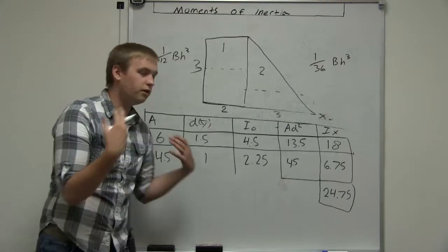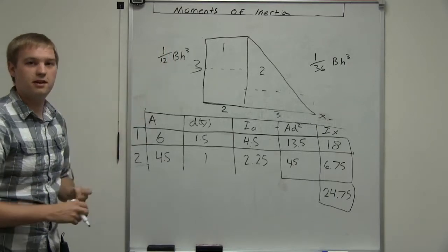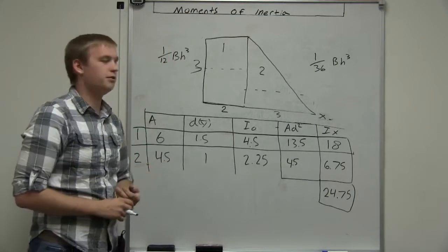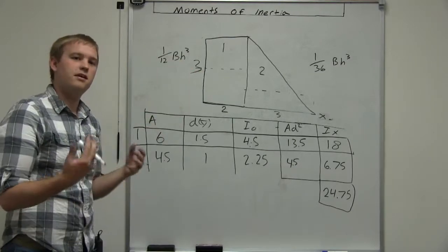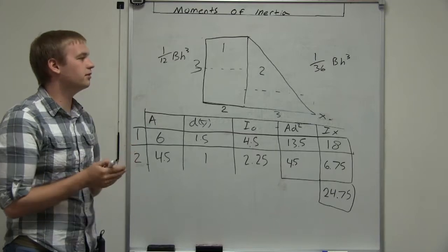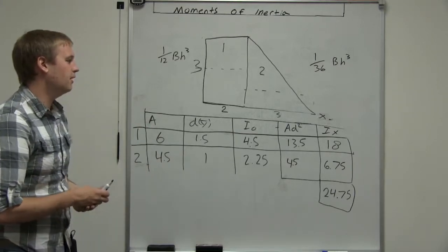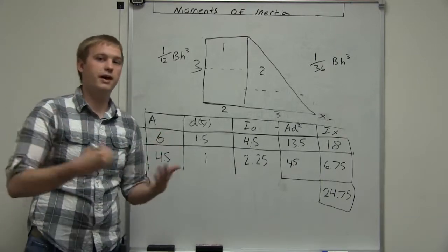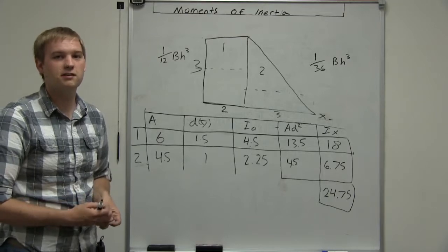Anyway, so what you'll be doing is you'll be given just this block or some object. You'll have to divide it into different segments, find the area or the moment of inertia, and then just add them all up and keep going from there. And in some of your problems, you could have up to 4, maybe 5 different shapes within one object.